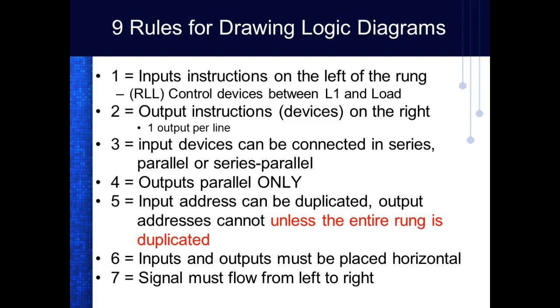So the problem we had is that the longer the ladder logic got, an input could change and go away before the PLC scanned the rung. So it would literally miss inputs. Well, what did we do? Well, we repeated the same rung several times down through the logic, but the rung had to be exactly the same. It had to be a duplicate of the previous rung. If you don't make it a duplicate, then you'll end up with some type of logic, right? It won't work the way you think it will.